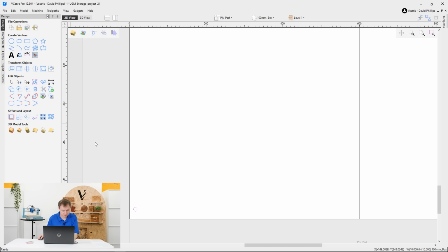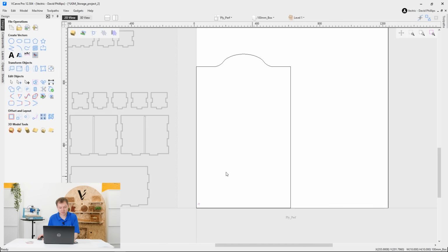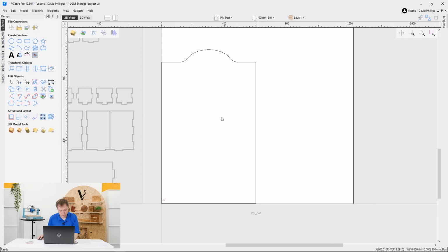And click apply. Now that's in position, we can look to use the array copy tool to make an arrayed pattern effectively with an offset included. This is just going to optimize the space, and it means you can add in different modular features to the backing board and offset them, so smaller items can sit next to each other.